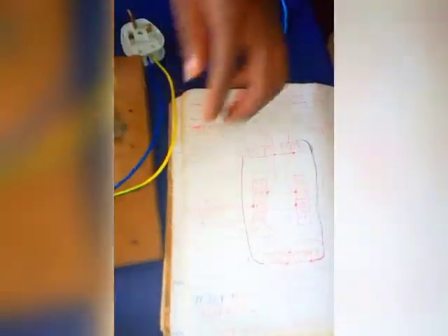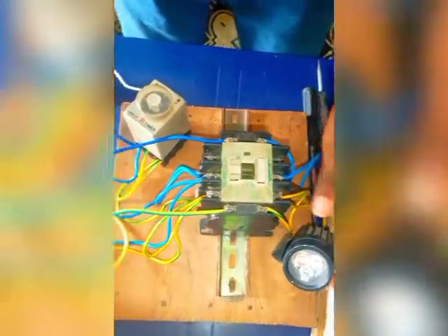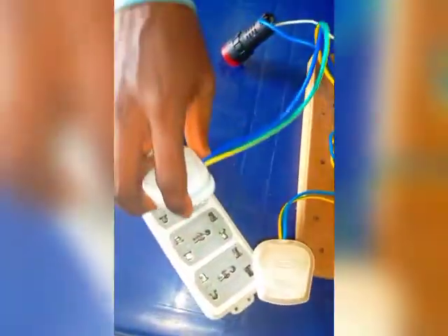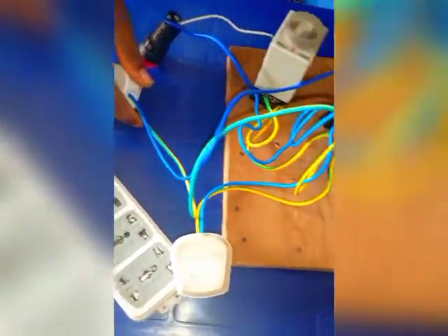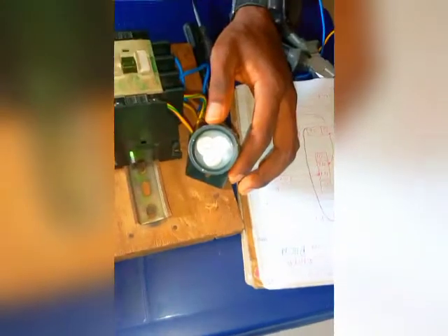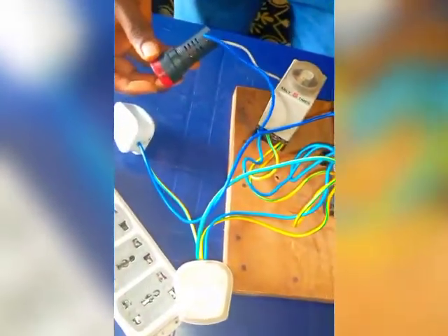So we are going to test now. What we expect is this: we are going to supply the generator first, because the generator goes with the normally closed, while NEPA, the utility, goes with the normally open. When the generator is on, immediately the load will start showing, which shows that the generator is on. Then when the utility supply enters, the alarm will indicate that there is utility supply, and you will not even notice it because it will immediately transfer to utility supply.